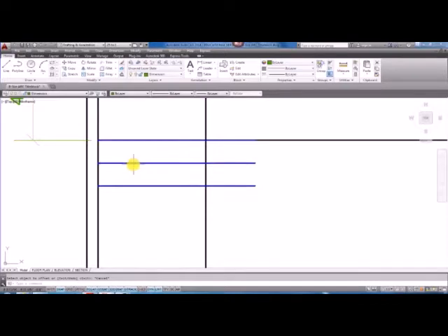It looks to me like we've got about a 1 inch hidden line here, and you can also see that it hit exactly on this mark right here, which is what we want. So I'm going to pull this back, and then I'm going to hit escape to clear that grip, and I'll pull this grip in. I can do the same with these, or I can trim them. And then offset those 1 inch.